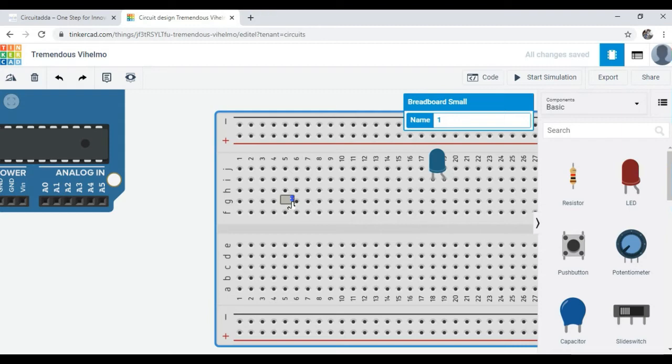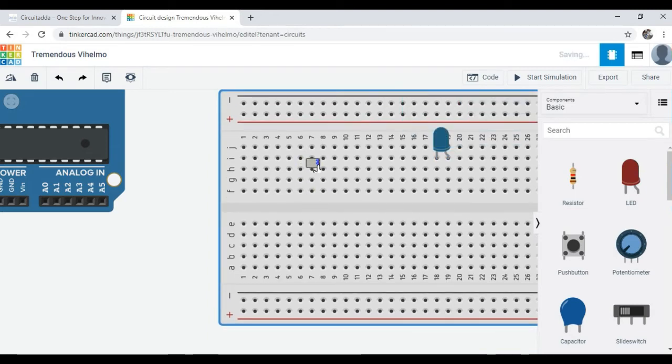That means the major application of this breadboard is to connect various circuits easily just by placing the wires between them, right? So if I use a pin in the seventh column and connect another pin at any hole in the seventh column, those two pins are short circuited in the background. But here I am using an LED, and in an LED, if anode and cathode get short circuited, then your LED is not going to work, right? So I am placing the anode in the 19th row and the cathode in the 18th column. These two columns are separate, so there is no short circuit because I am placing the two terminals in two different columns. So my LED is not getting short circuited.